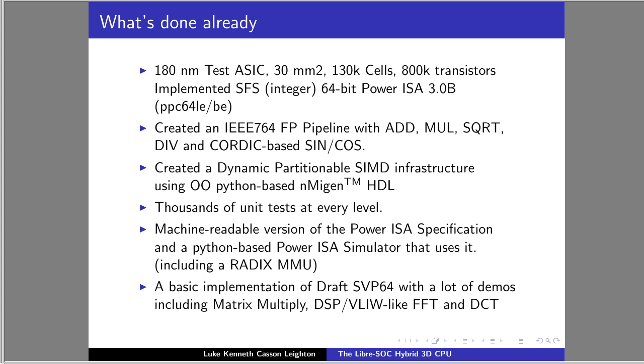It's really interesting, but the basic principle: the closest other processors in the world to what the FFT and DFT does in SVP64 are the Qualcomm Hexagon DSP, which has the ability to group, I think, up to 20 instructions into a zero overhead loop, where one of those is a decrement counter, the others are the actual multiply and accumulate associated with the FFT, and the other ones are load and store, obviously.